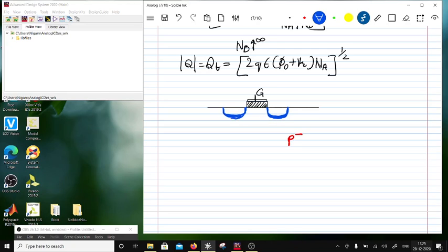So you have this portion which I am going to call N plus, and these terminals are interchangeable. They are source and drain, right? And besides that, there is another terminal which will be P plus, and then you will be interfacing this contact, which is body. So now this is an N-channel MOSFET.